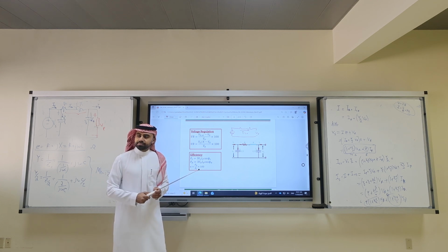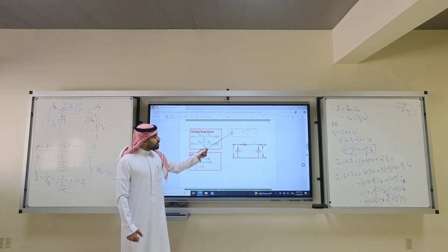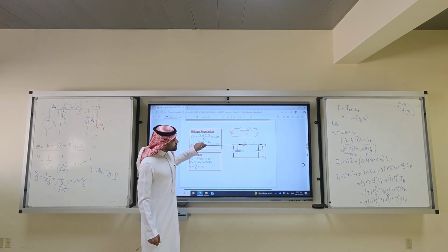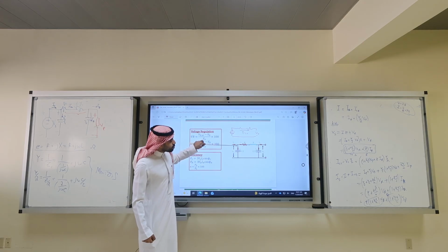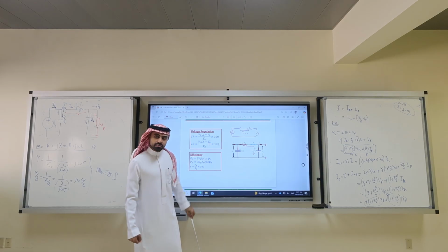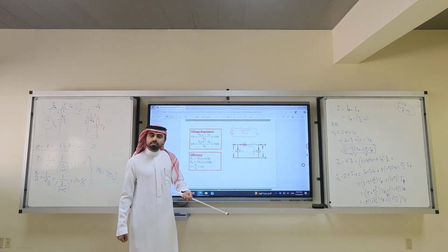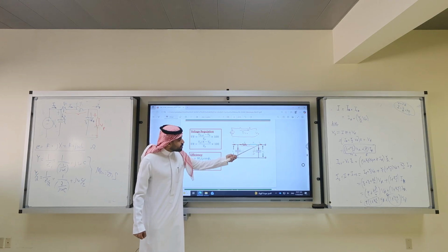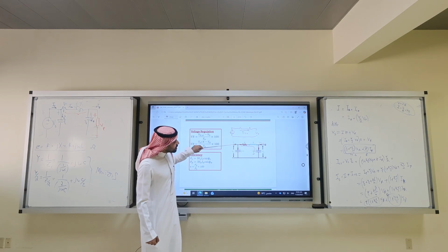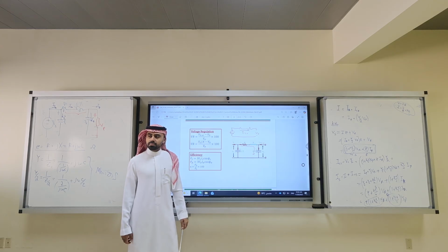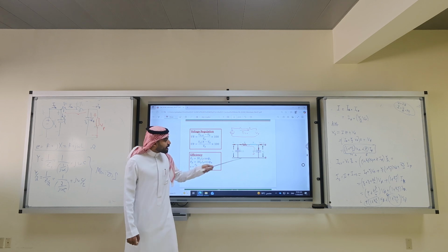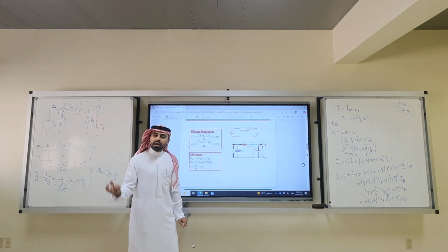For the medium line, if there is no load here, still there will be current flowing through this capacitor and through this line and this capacitor. Even though IR is 0 at no load, there is still current flowing in the capacitors. That's the difference between medium and short. Those parallel capacitors would take current at no load.